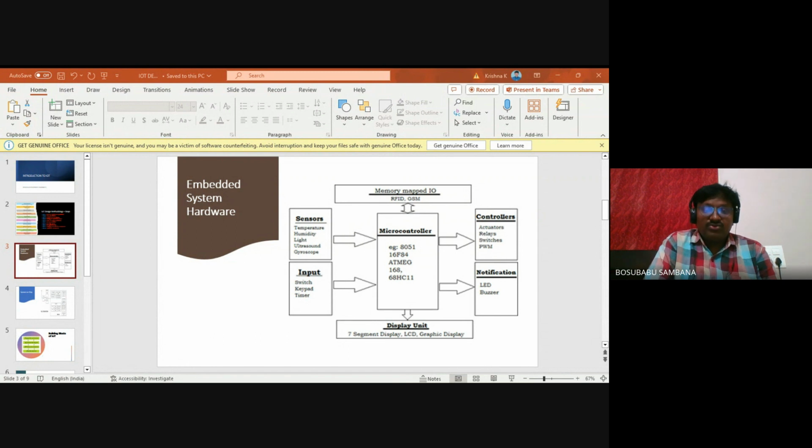The goal of low-cost IoT devices necessitates careful consideration when selecting the microcontroller to ensure that its full set of features is put to good use. The characteristics of the microcontroller that are most relevant to your project are bit depth; how quickly and accurately microcontrollers perform non-trivial computations depends on the register and data path width.